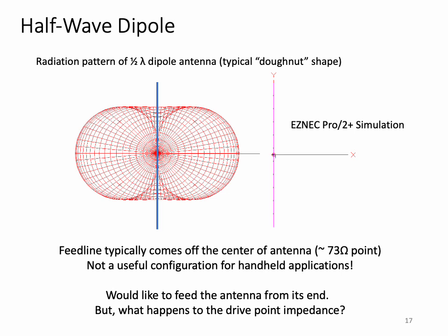Most of our experience with half-wave dipoles is operating them in a horizontal configuration. If we flip the antenna 90 degrees, as seen here, we have a vertical radiator which generates that familiar donut-shaped pattern as a function of azimuth and elevation. This pattern has a maximum intensity along the horizontal axis, which is ideal for terrestrial communications at VHF, UHF.